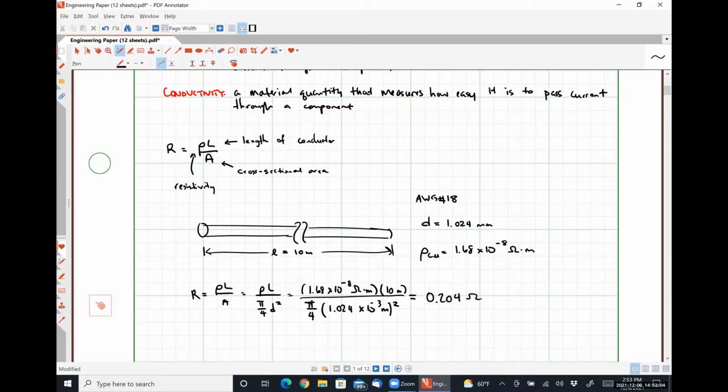In truth, they do contribute some resistance, but it's just so small as to not matter in the overwhelming majority of applications. Unless you're doing high power electronics and stuff like that, the length of a wire isn't really going to matter. So for those of you that go into mechanical engineering, working on setting up and maintaining HVAC systems, you need to make sure that the wires that you use to power that unit aren't so long that they cause a significant voltage drop, which will make your HVAC system run inefficiently. But for the overwhelming majority of us, this is never going to be much of a problem.